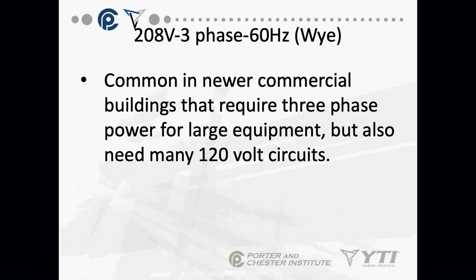Our school buildings, the newer campuses, including Rocky Hill, Waterbury, I believe York has it as well, and Hamden. You guys are running on 208 volt three-phase with the Y windings because of the number of 120 volt circuits. Anything else we get out of that, we're using transformers.